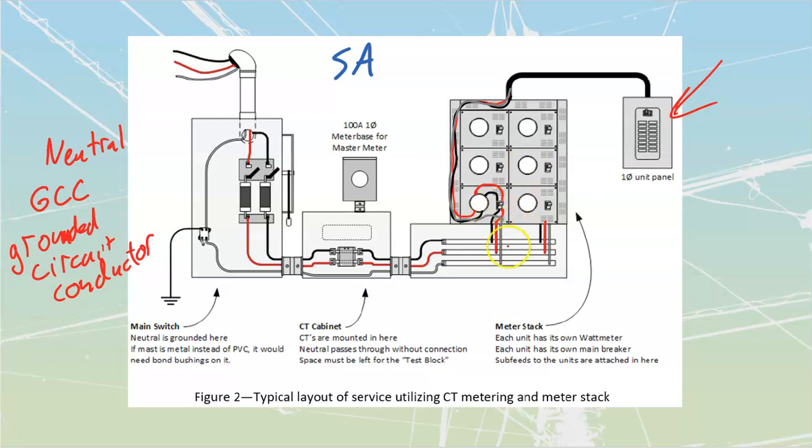It also allows us, as electricians, if we need to work on something, we can kill power up here so that we can work on the feeder itself, the mains of this panel, anything like that. Yeah, you could kill the main breaker inside of the panel and work on the actual panel itself, but if you needed to work on the incoming side of that single-phase unit panel, you would have to do that upstream. So it's a very common way that we go through these with the meter stacks.